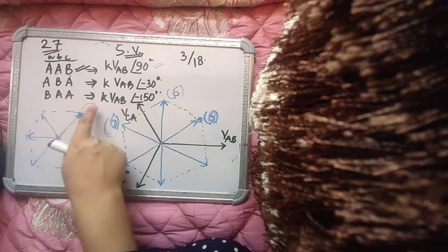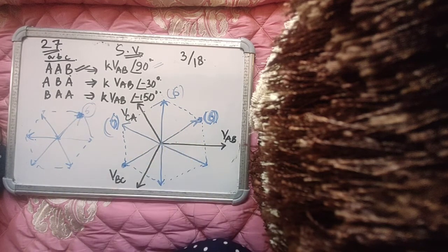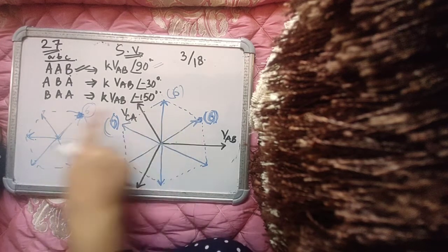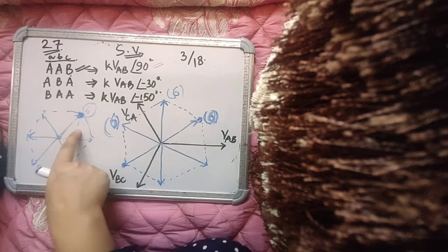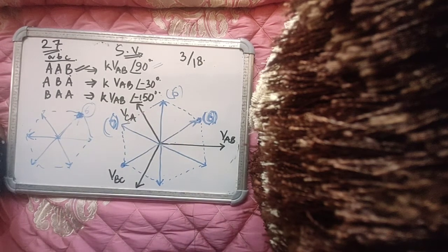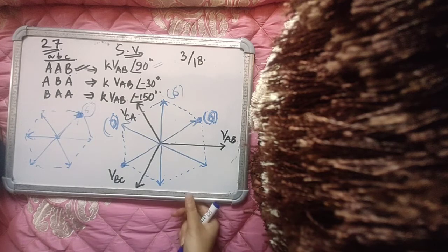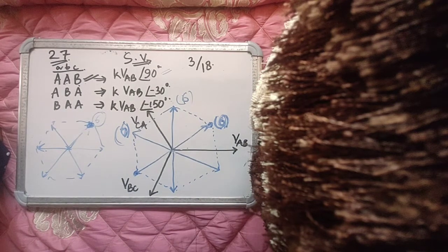Now there are 6 states giving you your best source current, and there are 6 states giving you your best load voltages. You will switch that state which is common to these two, which is giving you the best of both worlds. This redundancy basically helps you in controlling both source current and load voltage together. So both the space vector diagrams are run parallelly. I'm not going to go into too much detail because it will get too complicated, but if any of you is interested in its implementation, then of course we can sit together and discuss how it is to be done.